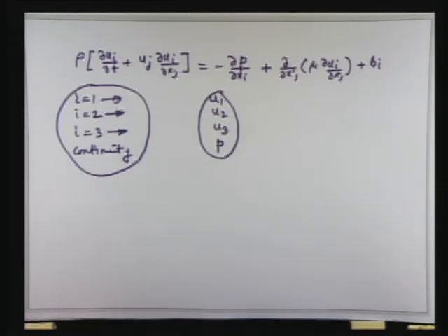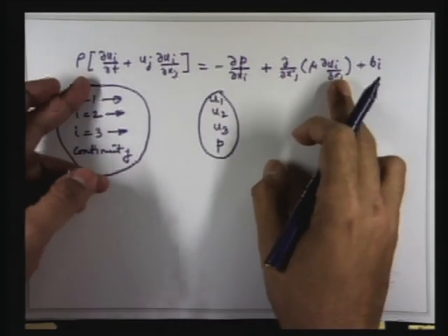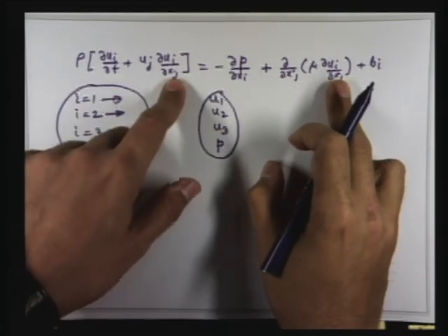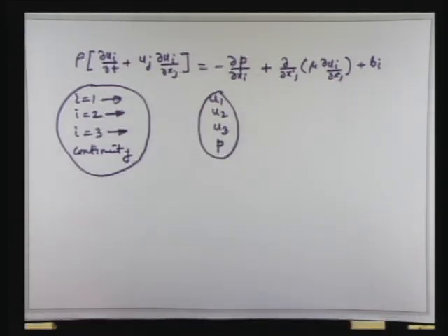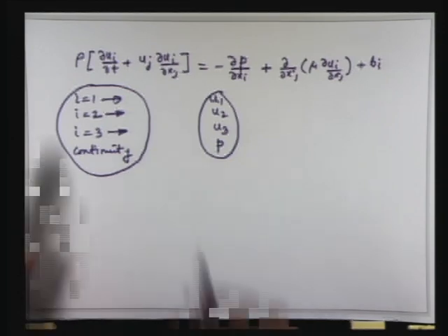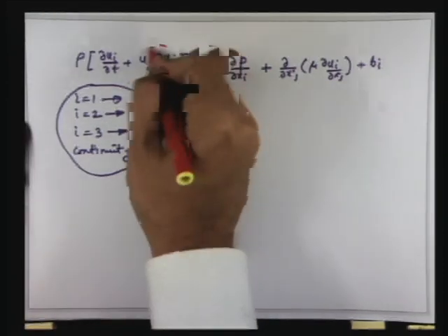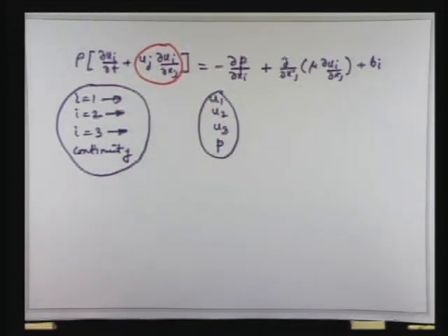What are the two important, and there are many interesting features, of course. First of all, see this Navier-Stokes equation, you can see from here that these equations are non-linear. So these are coupled non-linear partial differential equations. The non-linearity arises because of which? Because of these terms, like u del u del x, v del u del y, w del u del z. These terms give rise to the non-linearity in the Navier-Stokes equation.